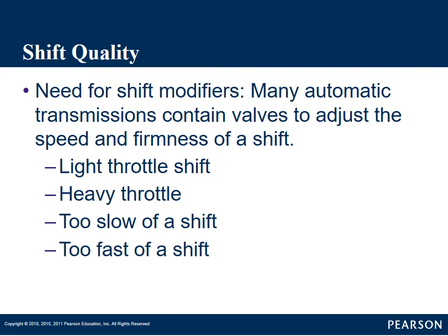That time is the shift. The slower you let that clutch pedal up on a manual transmission, the more that clutch slips. Yeah, you accelerate smoother, it's not so much bucking or a hard engagement, but it does slip that clutch.